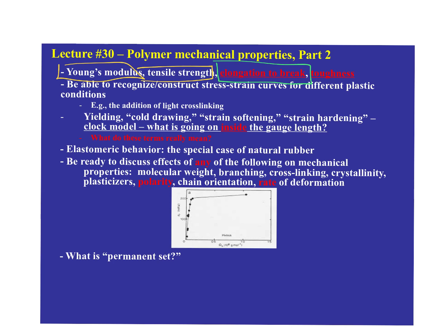We don't normally think about this with, they're certainly not ceramics and often not metals, because again, by the time it fails, the plane has already crashed. But in this context, we can have some utility in terms of elongation to break, because it reflects on the other component of polymers that's really important, which is toughness. All right, and so in some sense, what we used to think about in terms of just the inorganic side of things kind of has a counterpart in terms of this toughness-related aspects.